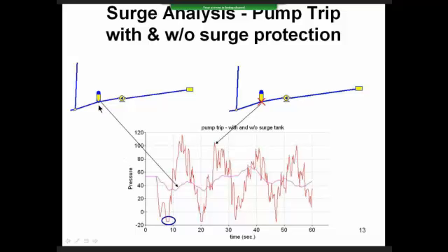But if you had a surge tank, which is shown over here on the left, when the pump trips, the pressure drops, and the surge tank is basically a storage of water under pressure. And so when the pressure in the pipe falls, the surge tank can provide water. And these events occur very quickly. So basically, we need to provide water until we get reflections back from the overhead tanks and so on, maybe only a few seconds.